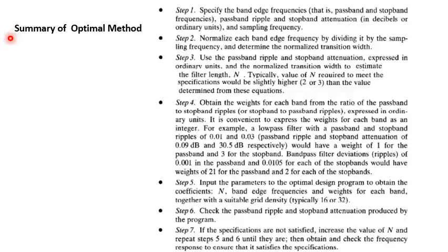Okay, the important thing is that typically the value of N, the length of the filter required to meet the specification, would be slightly higher, maybe 2 or 3 times, than the value determined from these equations.